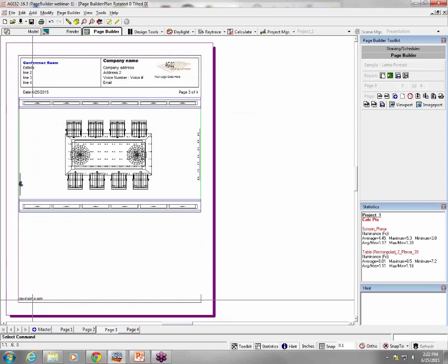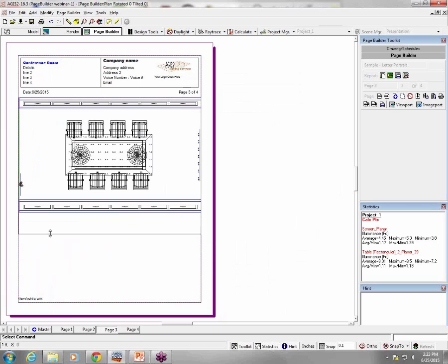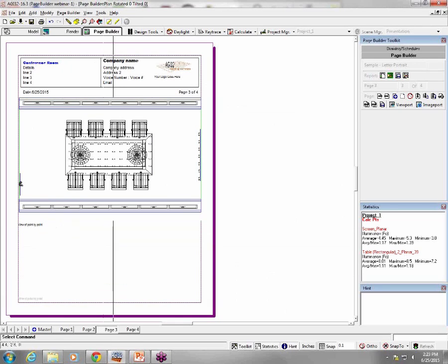It's pretty tall, right? And so we can easily change its size and or position. What I do is I'm going to move my cursor down here so it's just above where that description is. See that double-headed arrow? That means I'm at the edge of the viewport. So now I hold down my left mouse button and slide up, right? So that now it moves the description up, which looks a little bit better.